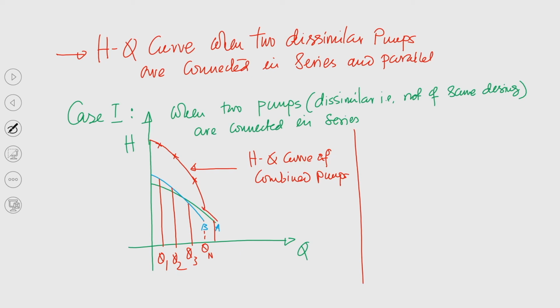Okay. So, you can understand, again I am telling, after this point there is no flow rate that will be supplied by pump B. So, there is no point of having addition of head. So, basically after this particular point, this line will cut over here, and the combined H-Q characteristic curve will follow the characteristic curve of pump A, and that is what.